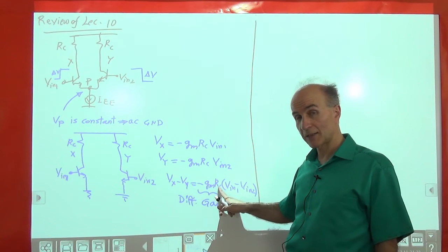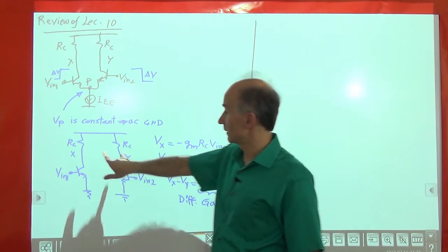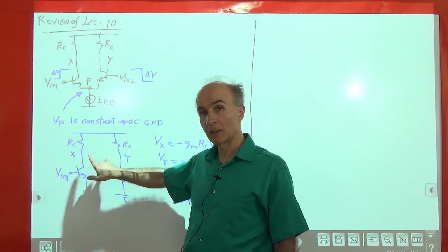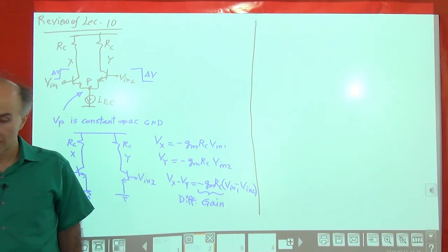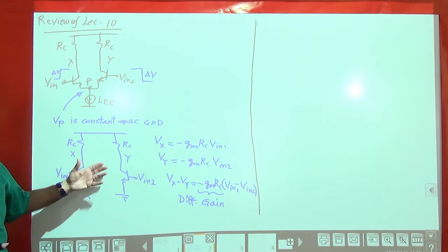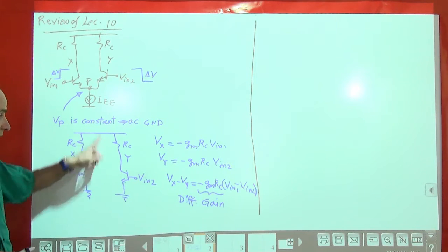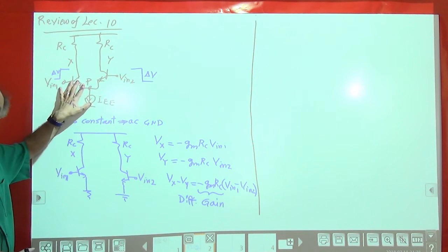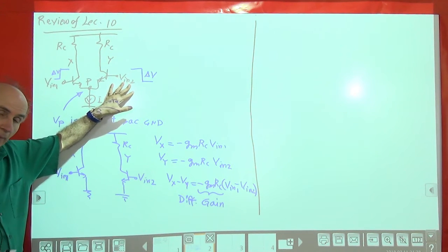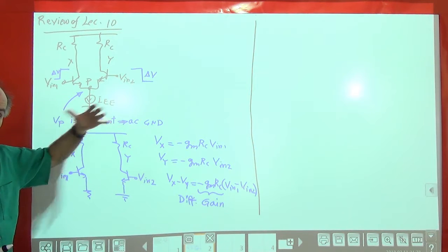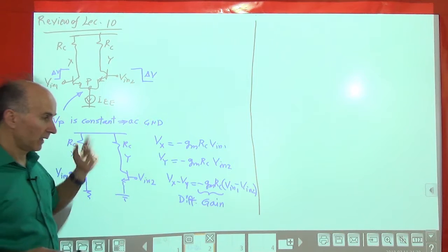And this voltage gain is called the differential voltage gain because we're taking the difference between the outputs and dividing it by the difference between the inputs. Okay, so that is a nice and simple approach to analyzing these circuits, provided that they do have symmetry, as we saw before, and also the inputs change differentially and by a small amount. So today we will try to build upon these ideas and look at some other circuits that have a similar behavior.